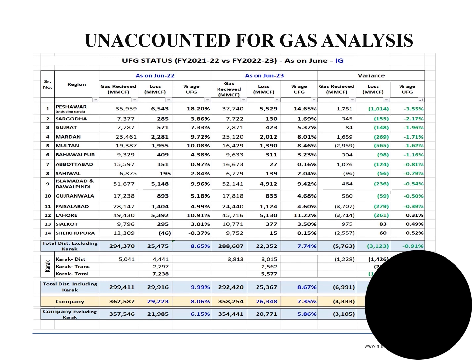Here is a quick overview of the unaccounted for gas, also called UFG: the gas which entered the gas pipelines but was not billed to a consumer. It means it just vanished within the system, within the pipelines. How does it vanish within a system? The gas has evaporated, or it's just leakage. There is leakage in the system, which is due to corrosion of the gas pipeline. So here is a quick overview of the SNGPL UFG analysis.